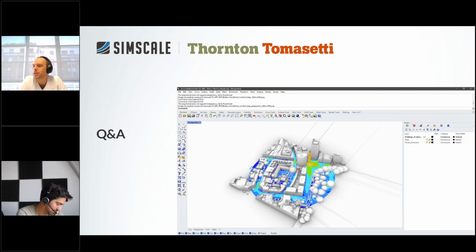No, it's a really good question, actually, and that's where I think different types of simulations and precision come in at different stages of a project. So the Lattice Boltzmann solver, without going into too much detail, is a different type of solver than most of the traditional CFD solvers. Traditional CFD solvers are often what's called finite element or finite volume solvers. They run on a CPU, your regular processing unit in your laptop, or could be on the cloud as well. The Lattice Boltzmann solver is a different mathematical engine, and it also runs on these graphical processing units, as Ricard was saying.